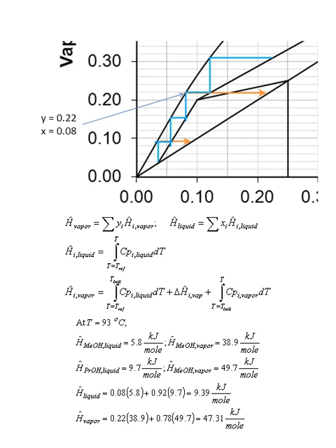In terms of the specific enthalpy of the liquid, we would use the integral of the heat capacity from a reference temperature to the temperature at that stage, and we integrate that between those two temperatures. For the vapor phase, we would do an integral of the liquid heat capacity from the reference temperature to the liquid's boiling point, plus the heat of vaporization, plus integrating the heat capacity of the vapor from the boiling point temperature to the system temperature T.